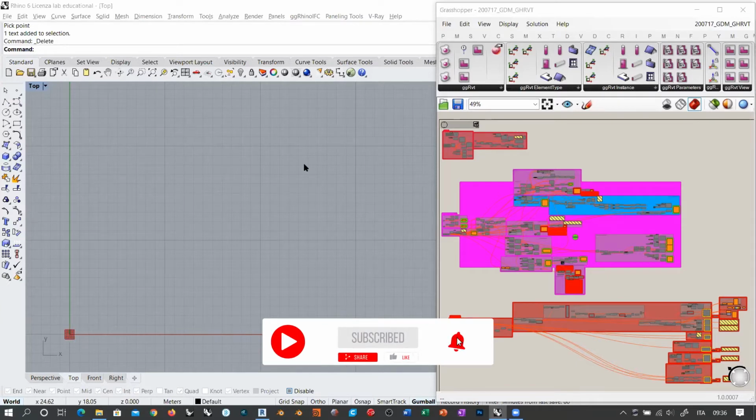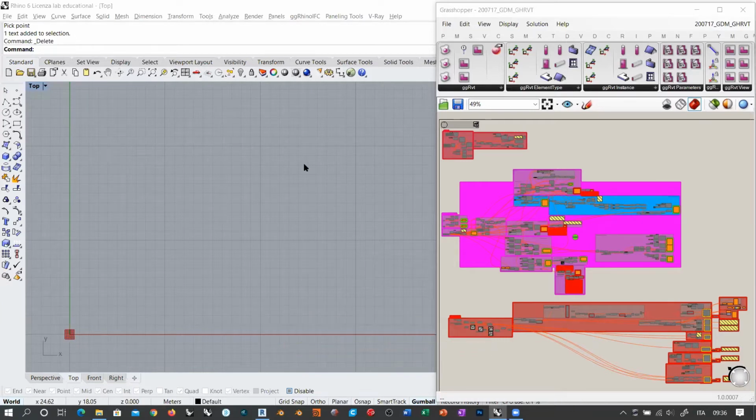IFC itself is another work in progress, and IFC is not only about Rhino to Revit interoperability. IFC is an exchange format that allows CAD software to communicate with BIM software, whatever they are. So you might want to use GSA, Robot, Revit, Tekla, whatever BIM software you are going to use in your workflow, be it an architectural BIM, a structural BIM, or something even more specific, like structural analysis. And IFC in that case is the exchange format.